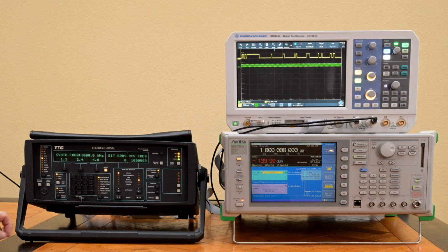If I boot it up after a couple of days, I would get an error that the time is not set and the date is not set. That's because the backup battery is empty in this unit. But I'm not really sure I even want to take the trouble of repairing it, because the manual explains that it only basically stores things like the time and the date and that type of parameters, and not any relevant test settings or calibration settings. So I don't care about that too much.